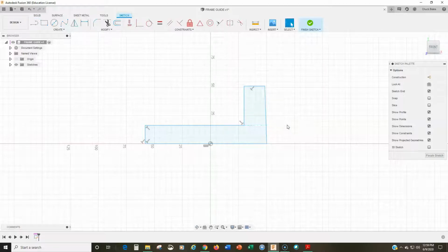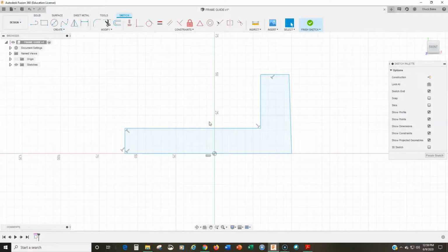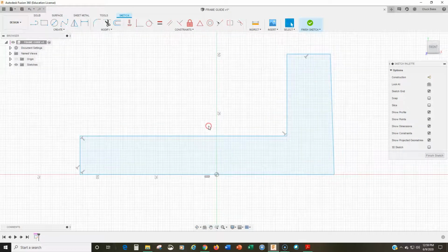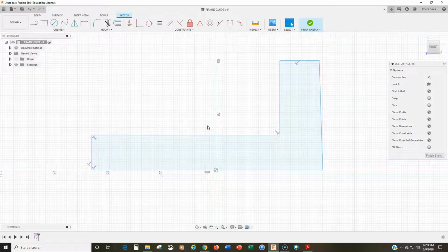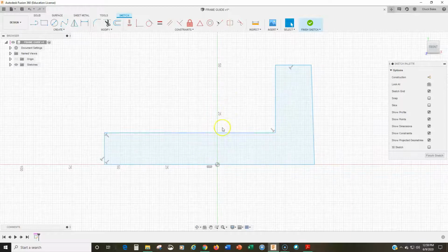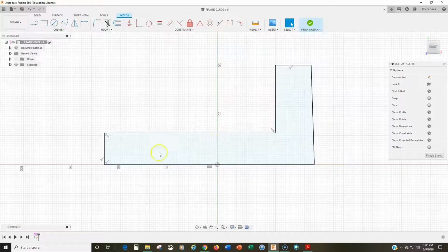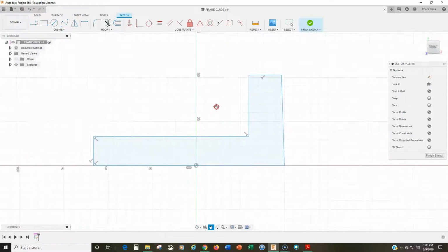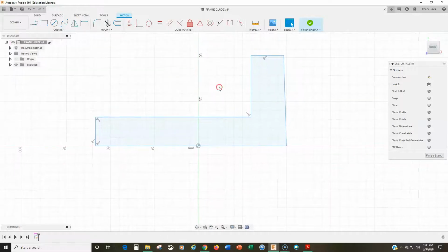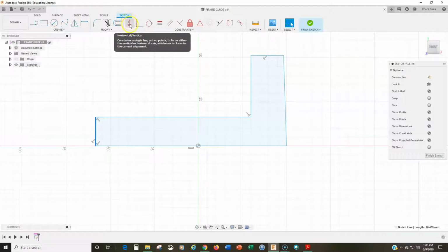This is not AutoCAD. So I'm going to finish the line command, hit escape, and then open back up here. So maybe before I put in those curves, because this is super easy to deal with, maybe I'll go ahead and add some dimensions to this, right? These are dimensional constraints. So now, while I'm doing this, let me add a geometric constraint.